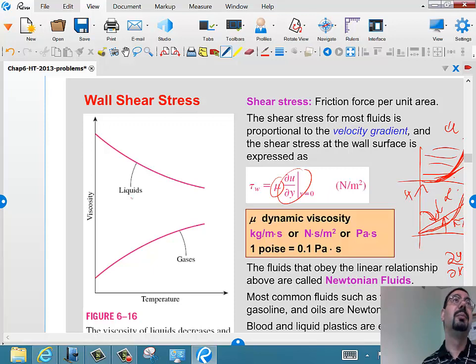They send very hot steam inside to heat the oil and make it less viscous, because as you heat the oil, the temperature will make the viscosity go down. So the shear stress would be much smaller. It would be easier to pump. Right? Especially when you are dealing with very heavy oil, like the one in Canada, very heavy oil with sand, they push very hot steam, and that helps the oil to become less viscous.